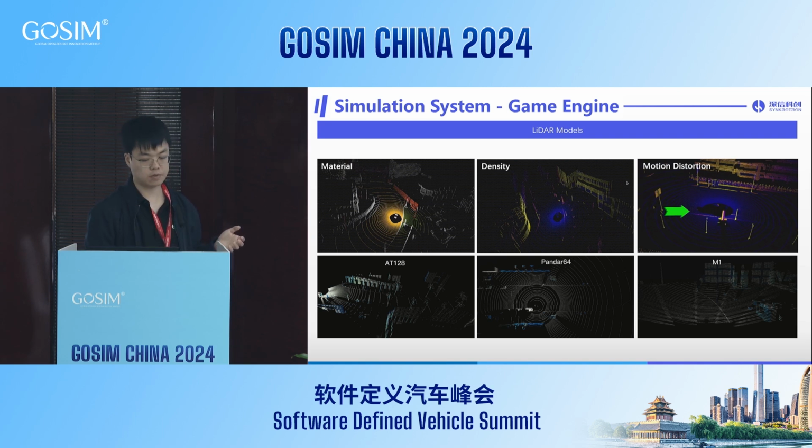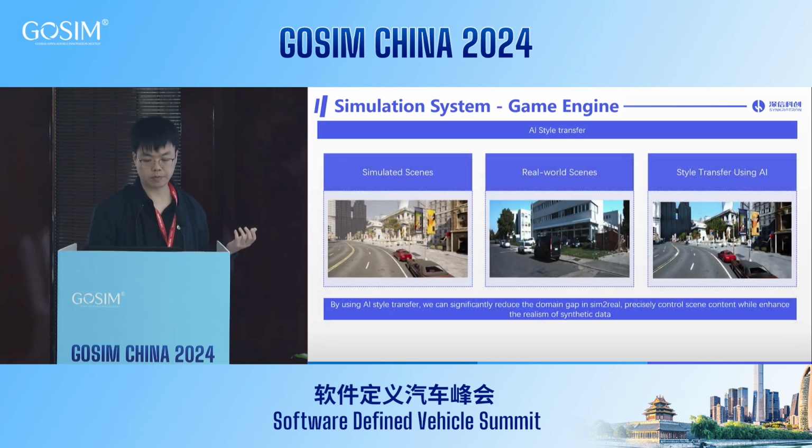At the same time, different LiDAR uses different wavelengths of laser light. So you need to consider different reflection coefficients on different kinds of materials for each of these wavelengths of laser. Those are all based on physics, directly modeling how the sensor works.